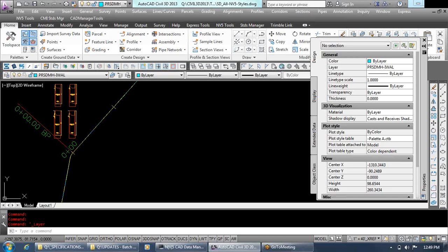Okay. So that does bring up the point that you really shouldn't be using the standard text style for anything else. It just needs to exist in your drawing as is, because a lot of things start to use it, especially Civil 3D label styles. All those have to use a font, and right now they're all pathed to the standard font.